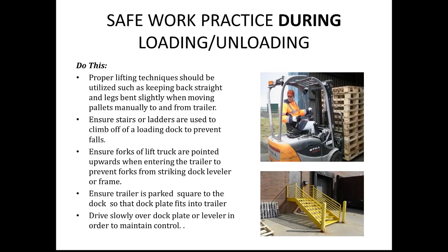Another is that you make sure that under no conditions do employees jump off the docks, for any reason whatsoever. It could be to clean garbage out of the dock bays or whatever. That's a recipe for somebody really getting injured. So in order to do that, the employer must ensure that there's proper egress. So you have a proper stairwell and access to a door so that they don't have to jump off the docks.